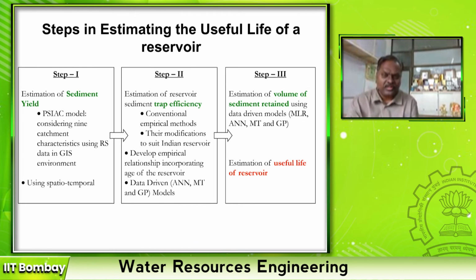Once I have this measured volume of water for different levels for a longer period, or the volume of sediment deposited measured for a longer period, then we can apply our data driven techniques to estimate this trap efficiency. Then the third step is to estimate the volume of sediment retained, and from that we can estimate the useful life of a reservoir.